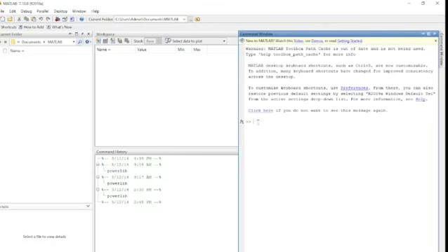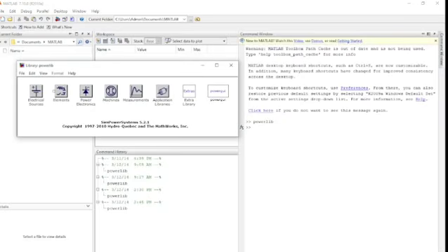this is a command prompt that you'll get. On the command prompt, you have to type your first command, which is for opening a library window called the power library. So you have to just type powerlib, press enter, which will open the power library window. This library window is used to create different circuits.